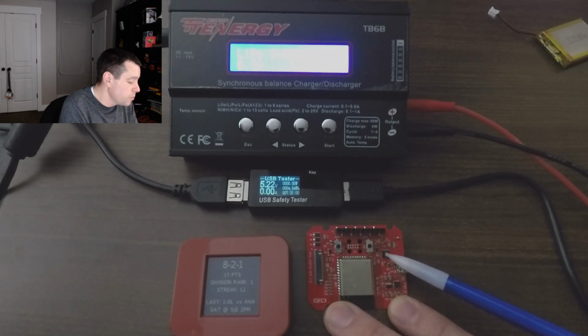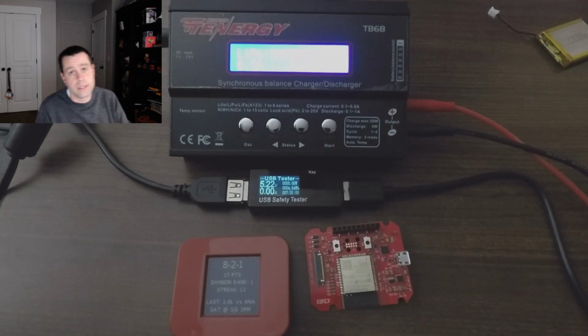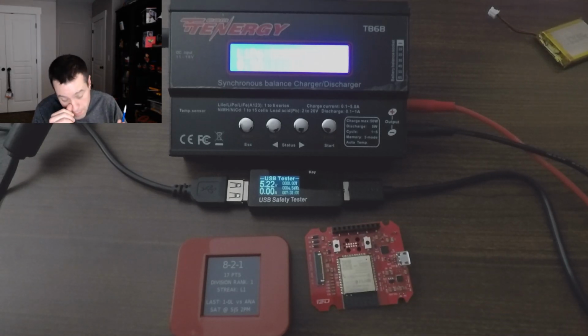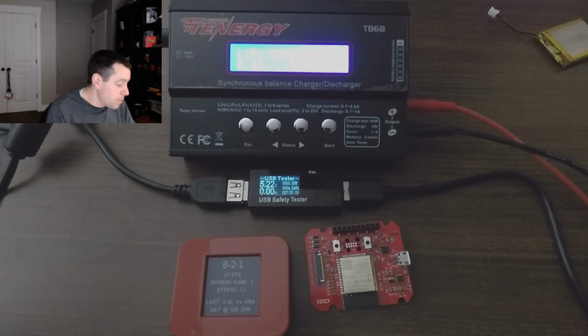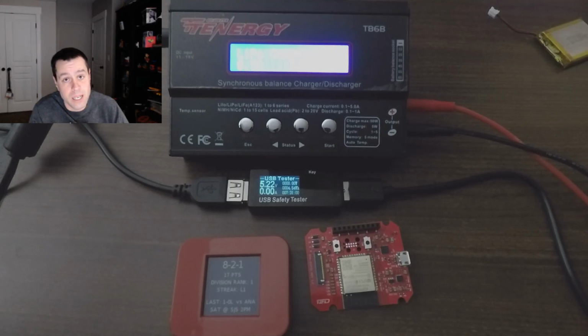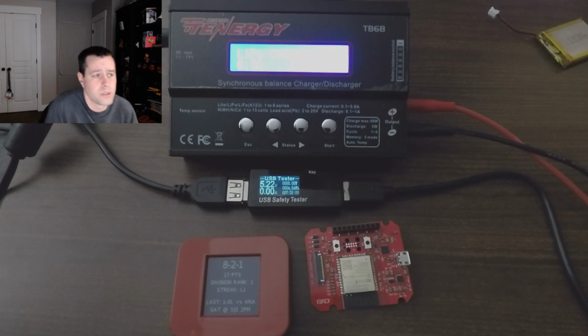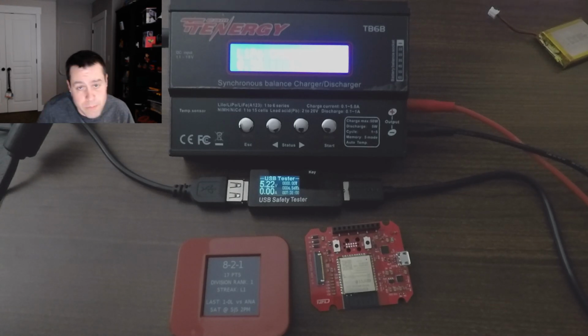And so this, when you plug it into a computer, is going to register this entire device as a USB device. It'll actually show up as a virtual COM port for those that are familiar with that. But by default, and I learned this from the data sheet for the FTDI chip, it's only going to request, I believe it's like 98 milliamp. Which doesn't make sense because you have to request them in unit loads, so in 100 milliamp increments. So that's weird, but the data sheet definitely says something less than 100. It's like 90 something milliamps is what it requests by default.